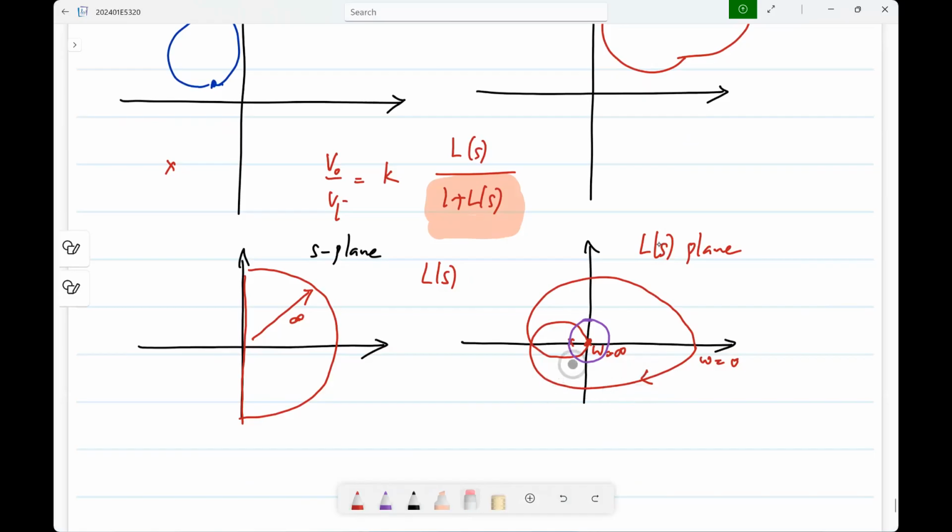And you see when the curve enters the unit circle. Like I said, the loop gain always goes to 0 at infinite frequencies, so this contour will go to the origin, or the magnitude will always fall below 1 at some point. And you see where it goes inside the unit circle. If it goes inside the unit circle in the second quadrant, it must have crossed over like this and then it encircles minus 1, 0. That's the idea behind this phase margin.